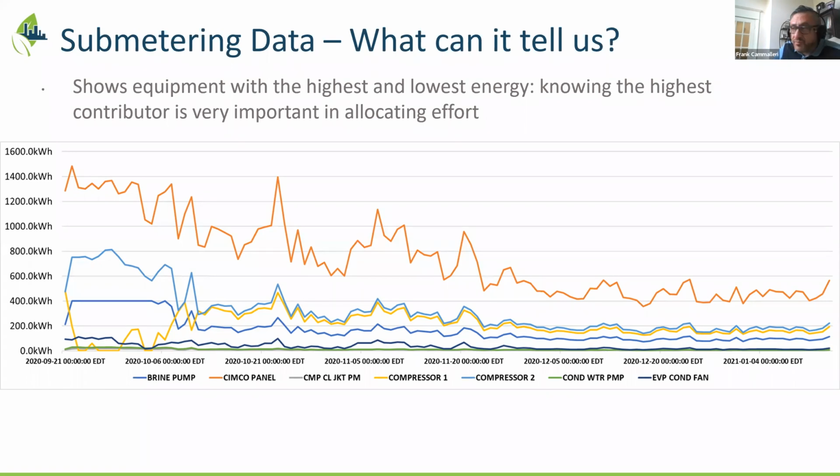So one little tidbit of information that I'll share, some of you may or may not know this: we talked about the compressors being the biggest load here. There's a strategy where you run your condensers a little bit harder. You might get a small increase in that energy, but because it's so small, it is more than offset by the savings you get from running your compressors more efficiently.